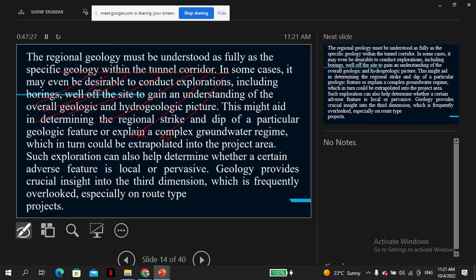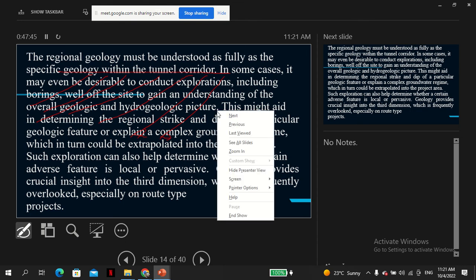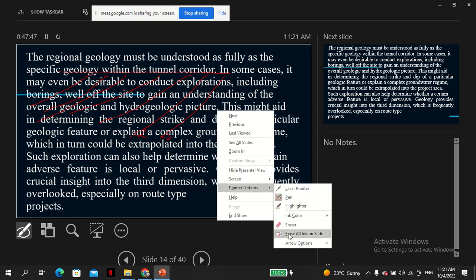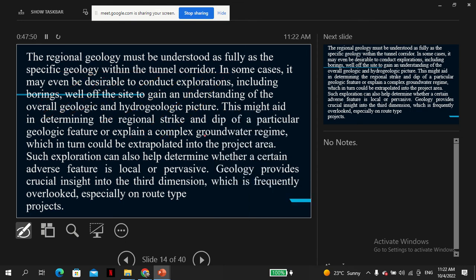So you can meet all manner of ground conditions, and more often than not we encounter stratification, we encounter rock that have strikes and dips, as already explained. So all these things affect the strength, and as a tunnel engineer, you have to be aware and have mitigative ideas. Also, the issue of the presence of water is important as well, as I've explained.